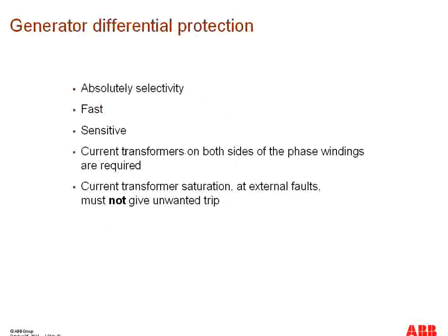Let's talk now about the differential protection itself. Differential protection, as with all other differential protections employed, whether it's a transformer or a line protection, has the foremost quality that it is absolutely selective, and the protection zone is defined by the location of the CT.